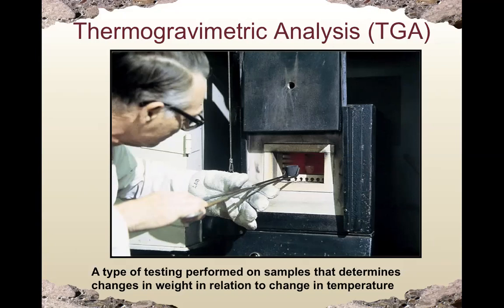So over time, we know at a certain temperature how much weight loss the sample will experience. Because for certain types of chemicals, that chemical will evaporate or transform into gas at a certain temperature. For example, for calcium hydroxide, it will decompose at, for example, 800 degrees Celsius.